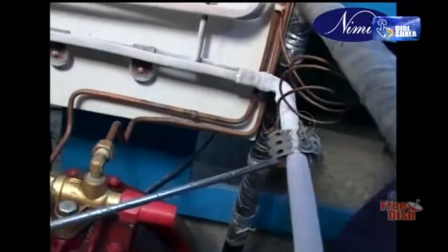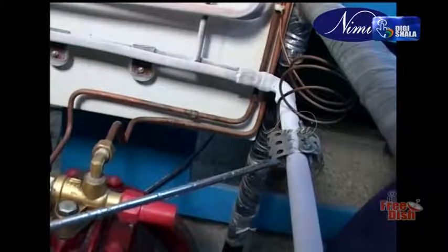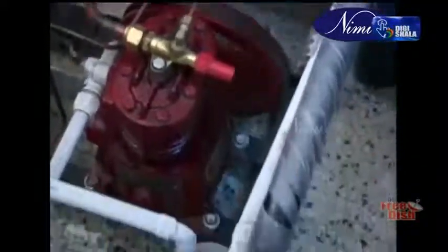The thermal bulb of the thermostatic expansion valve is clamped with the suction line. Here, the refrigerant liquid changes into a low temperature, low pressure state and enters into the evaporator to produce the cooling after boiling at low temperature.